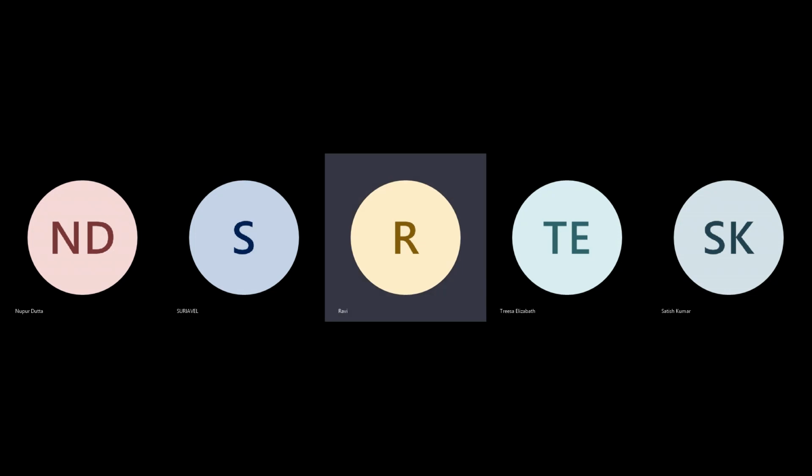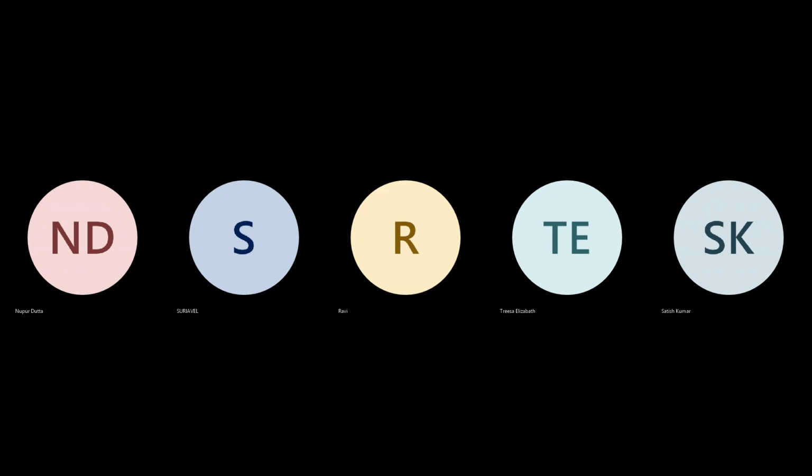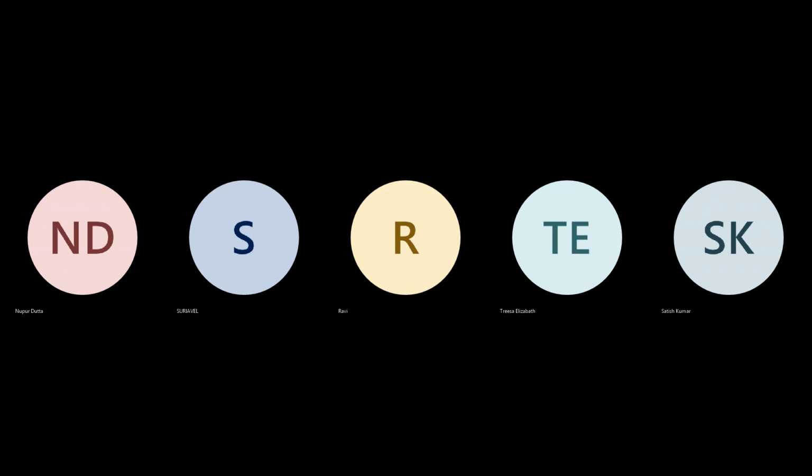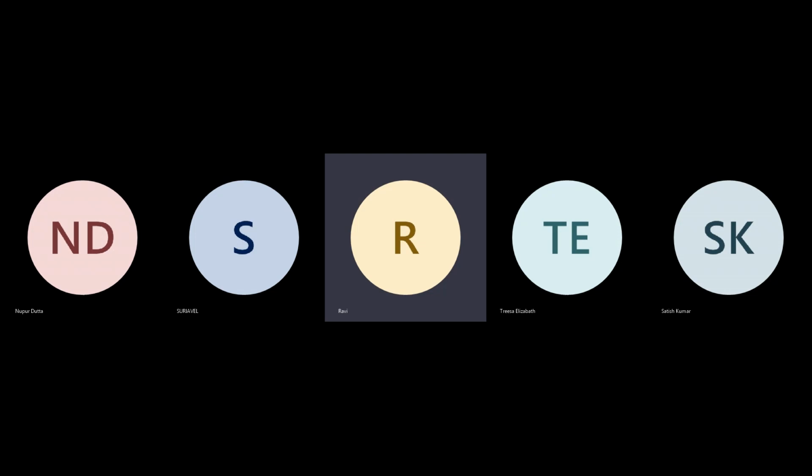You understand? These are the things that you should track when you're looking at the log file. Because the tool is doing things automatically, you wouldn't observe what it is doing or how it is doing it. Placement only will take 3 days. You should expect the placement to complete overnight. Sometimes it takes more than 2 or 3 days. That is the expected data.